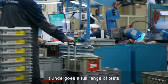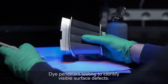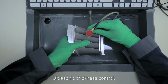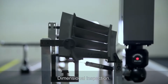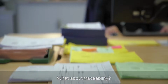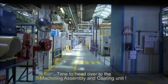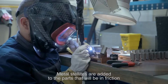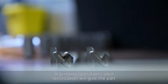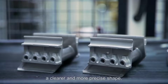It undergoes a full range of tests: macro control to inspect the grains, dye penetrant testing to identify visible surface defects, ultrasonic thickness control, dimensional inspection, and internal health control by digital radiography. What about traceability? Time to head over to the machining assembly and coating unit. Metal stellites are added to the parts that will be in friction to reduce wear and tear. A grinding operation called rectification will give the part a clearer and more precise shape.